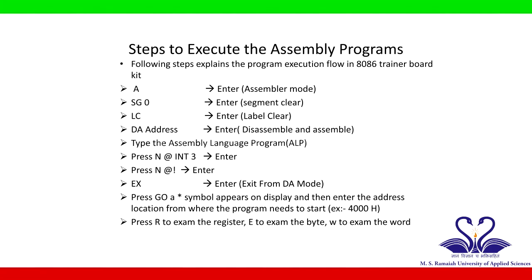Type DA. Enter deassemble and assemble. Type the assembly language program ALP. Type N at INT3. Enter. Type N at exclamatory. Enter. Type EX. Enter. Exit from DA mode.